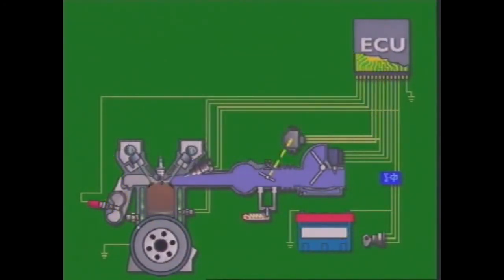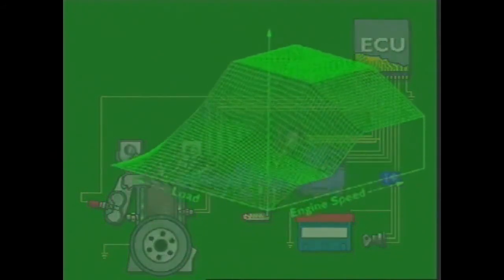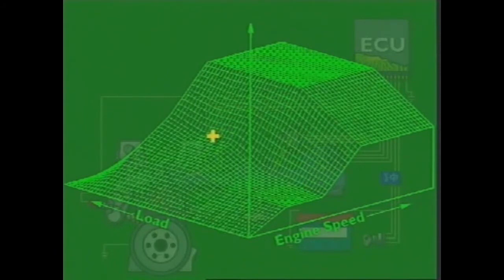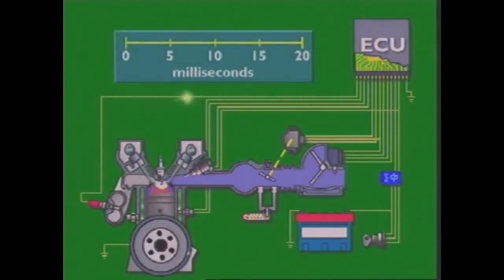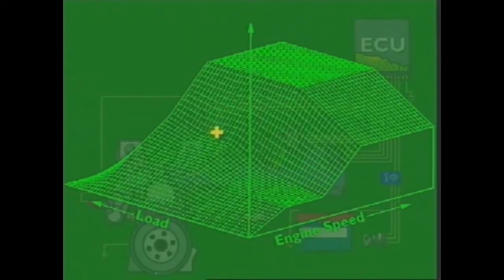This vehicle is using medium throttle with light loading and mild acceleration. Its control unit will set fuel delivery for a specified pulse width. However, if fuel pressure is less than when the vehicle was new, feedback from the oxygen sensor can cause the lambda control to increase injection time.